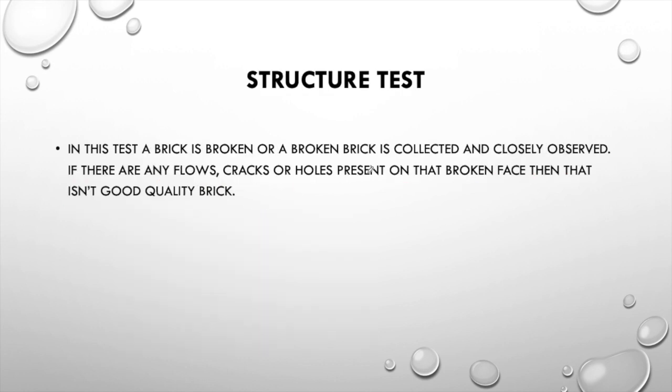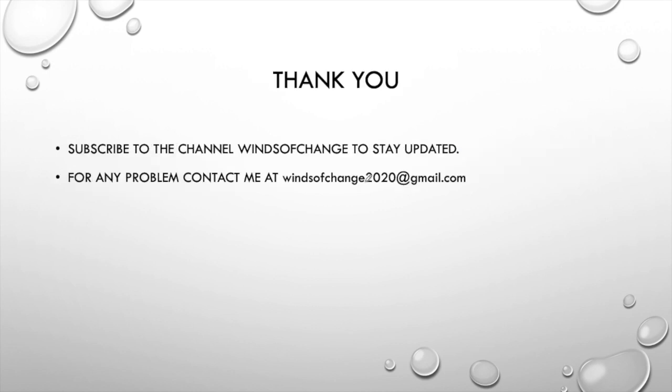Now the structure test is that in this test the brick is broken, or broken bricks are collected and closely observed. If there are any flaws, cracks or holes present on the brick faces, then that is not a good quality brick. Here we will finish with the subject of bricks.